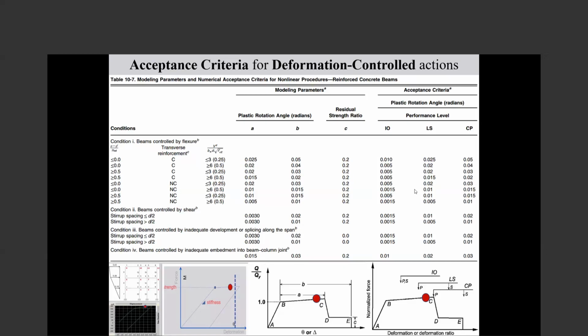This part is steel, this part is concrete, this part is, for example, alloy. Then the program finds the neutral axis based on the mesh that you provided.